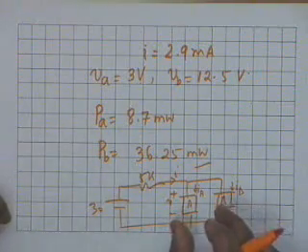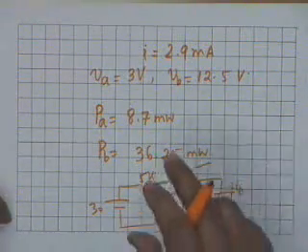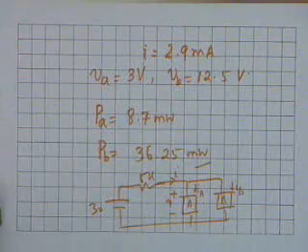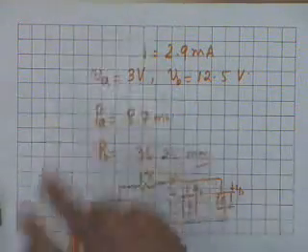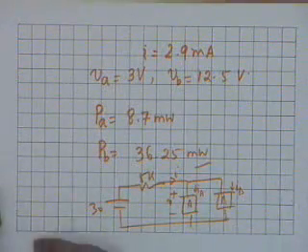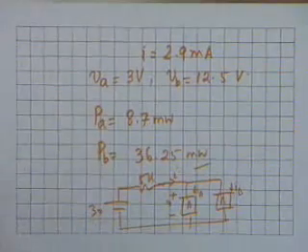All that you have to do now is to fix the voltage. To draw the characteristic, take a certain voltage, draw a vertical line and see what the values of the currents are in the element A and in the element B. Add the two currents, that gives you I, and therefore you can plot V versus I. Then on this plot you draw the load line, mark the intersection, that gives you V and I. Then you divide between IA and IB.